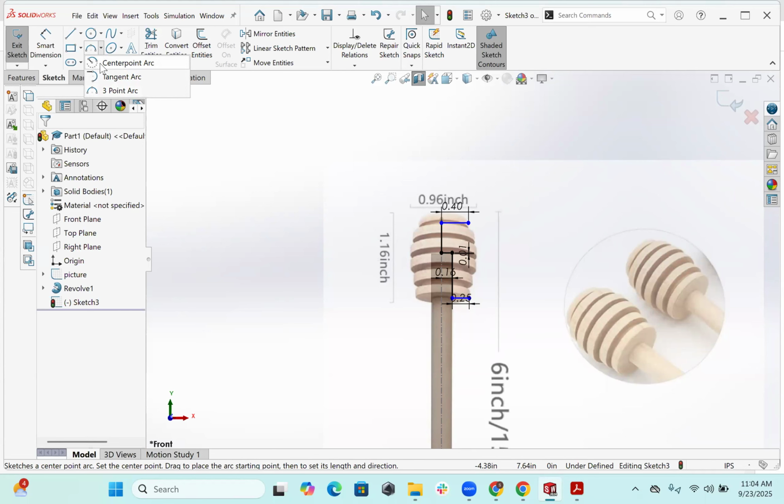Okay, something that I wanted to mention to you guys. So if I grab the side line and go here, and we have our stick. And as you can see, the solid body is revolve one. And then the second one we added shows up as revolve two. One of the reasons that this is doing that automatically is because these two don't touch. So we have a gap here. If they were touching, it would automatically combine them and make them into one solid body.